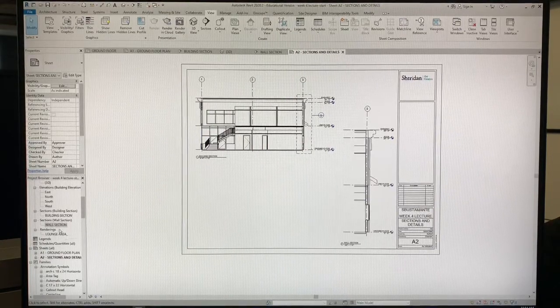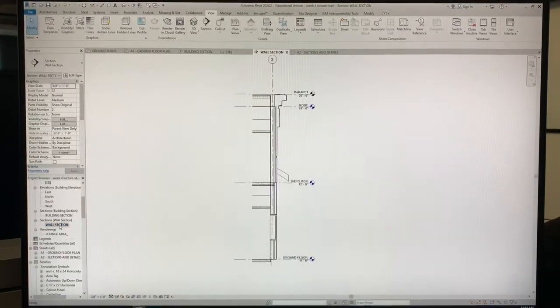Now go to your wall section. I want to zoom in to this area, here, and lastly, here. I want to create some details of my foundation connection, my floor and wall connection, and my roof connection. So no problem. Call outs. Create your call out.